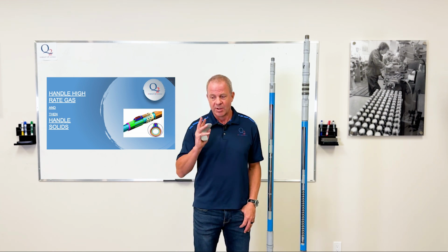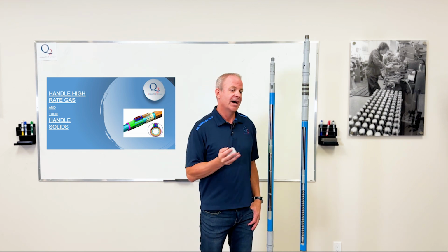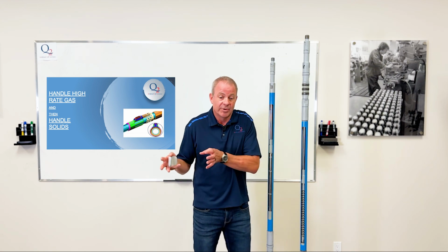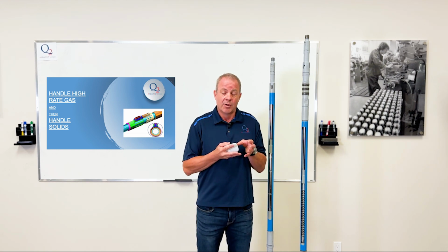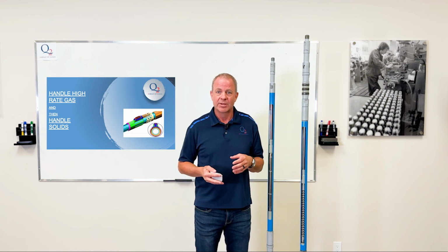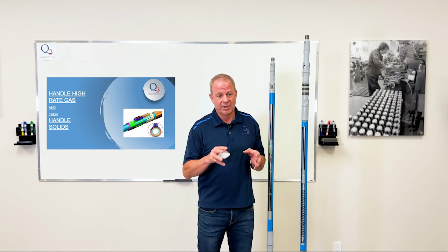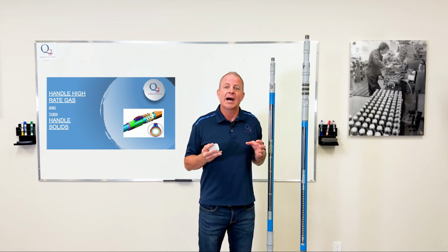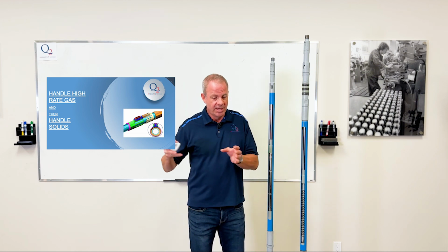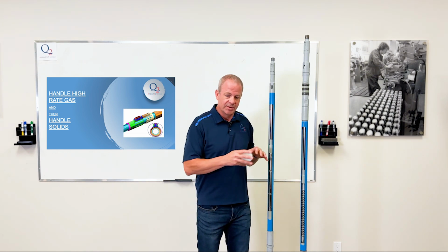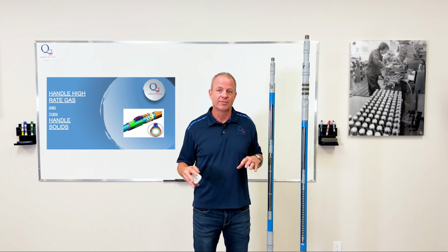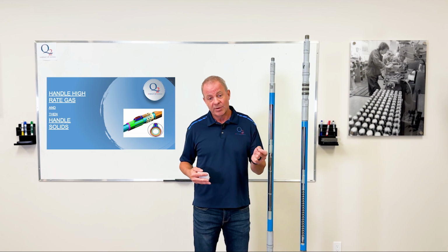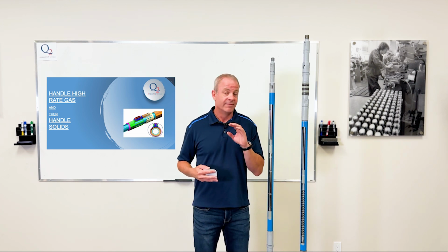The reason I say this is that once you get a flush of gas that comes in from the horizontals and the build sections, guess what? High velocities, that's going to bring a slug of solids with it, right? When you have just liquid and its flow rate, you'll see that the solid accumulates on the bottom of the wellbore, and I'll get into that slide in a bit. But once you have a big flush of gas and oil and everything that comes up, that transports all of those solids that have been peacefully lying in the build section and the horizontals for a long time, and that's usually when we see these pumps lock up. So startup procedures, casing pressure, tubing pressure, when you start these up, are very, very important.